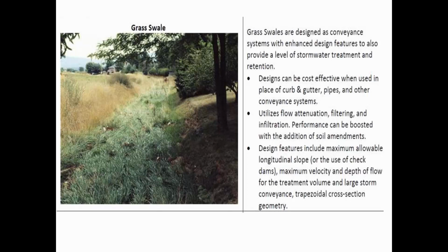Slower. Exactly, yeah. It's because this grass sticking up into the flow has a higher n value, so the velocities are going to be decreased. Also, there's the advantage that the grass is going to keep the sediment in place, and so scour and erosion is a real problem in streams. If you can get grass to grow because you've got enough sun, in a lot of places here this wouldn't work because you've got a tree canopy over the ditch, and so there's just not enough sunlight for the grass to grow. But there are spots where it will, and where it does, it helps to prevent the channel from being damaged during big peak storms.